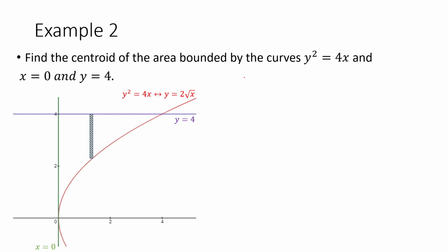Okay, so next step is again we're going to determine bar x and then area. So that will be x sub c times the differential area. So again, since we are using vertical strip, this becomes x sub c and then y top minus y bottom dx. So we need to determine x sub c.